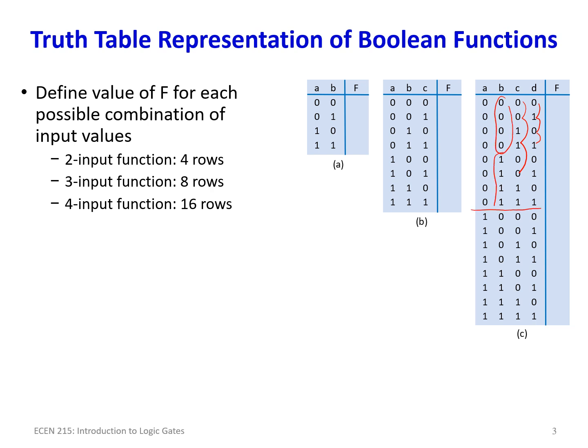And this next one, it's always half. This oscillates at half the frequency of this one, and this oscillates at half the frequency here. So that's a way to quickly do this. Another way to represent this, by the way, since this is 4 bits, is hexadecimal, which is 0 through F, where this right here is A. This is 9.